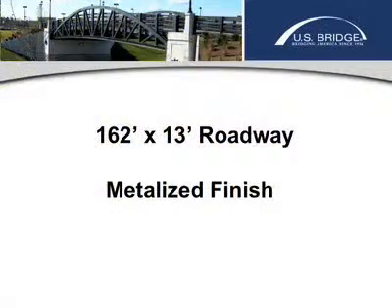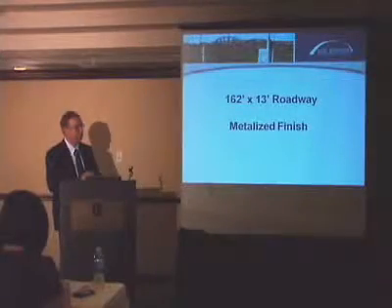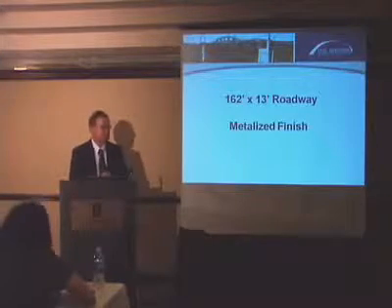Another bridge that was worked on was metallized. A metallized finish is a galvanized coating that is thermally sprayed on the steel pieces. I prefer first the hot dip galvanized.